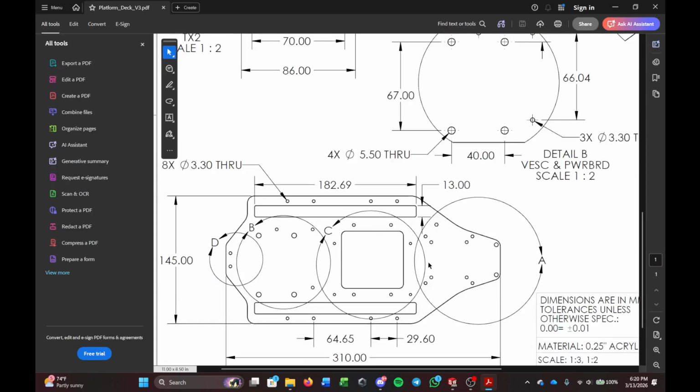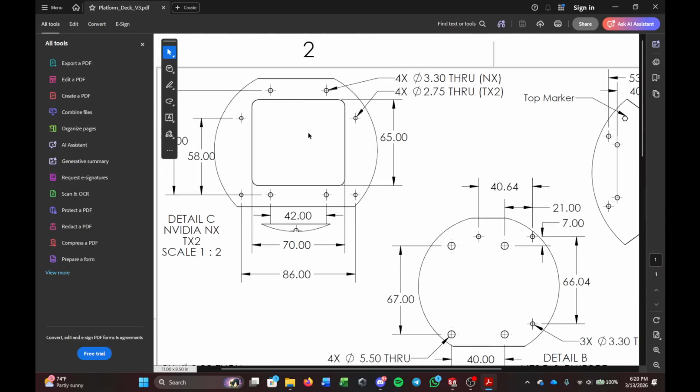We have a good amount of holes to make, but I should be able to take advantage of the mirror tool again, so we're gonna try that here. Because if we look closely at the wire slot, if I were to put a line down the middle, I'll see that the holes are symmetric. So that can save me time instead of making 6 holes. I'm gonna make half of these and then we'll mirror it over.